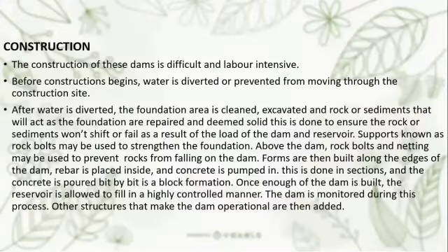And construction. The construction of this dam is difficult and labor intensive. Before construction begins, water is diverted to prevent it from moving through the construction site. After water is diverted, the foundation area is cleaned, excavated, and the rock sediments that will act as the foundation are repaired until deemed solid. This is done to ensure the rock or sediments won't shift or fail as a result of the load of the dam and reservoir.